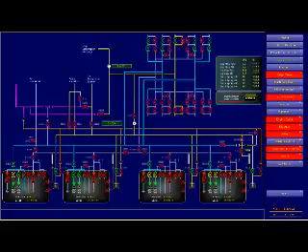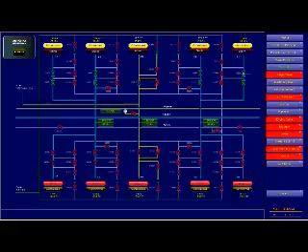Suppose now the pressure is 5. And if it comes down to 3 bars, then... Forget kPa. 3 kPa. I start thinking at 4.5 kPa we should start getting worried. Let's see the manifold pressure, because if the manifold pressure is, I mean, 12 kPa, it is good enough. So the only thing you can do at that stage maybe is reduce the discharge rate. Either switch off the pump or reduce the flow rate.